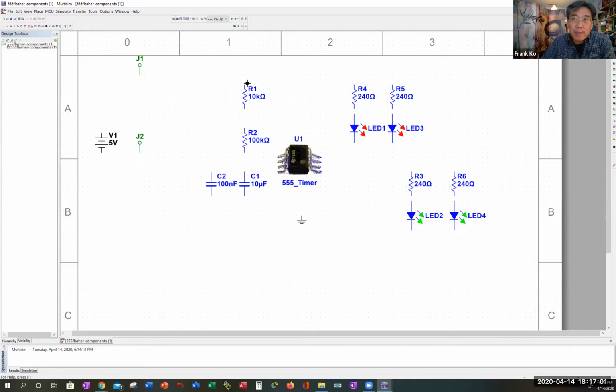So I'm going to connect the top of R1 to the top of R4 and R5. I move my mouse pointer, which is an arrowhead right now, and place it at the top of R1. The cursor changes from an arrowhead to a black dot with a crosshatch on it. I click, pull a wire up, following the grid mark, just a little ways, pause, click again, bring it all the way over to here, above R5, click, bring it down and click on R5. Now I've got a connection between R1 and R5, yes?